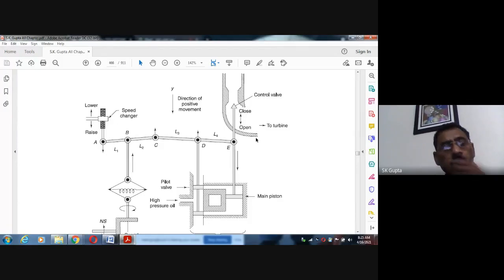Now, as we told, again we are repeating, if the load was high, because of this process, these are the different limbs, because of these limbs, more high pressure oil was entering the hydraulic amplifier, and more fuel was able to go in. At that time, input was equal to output.